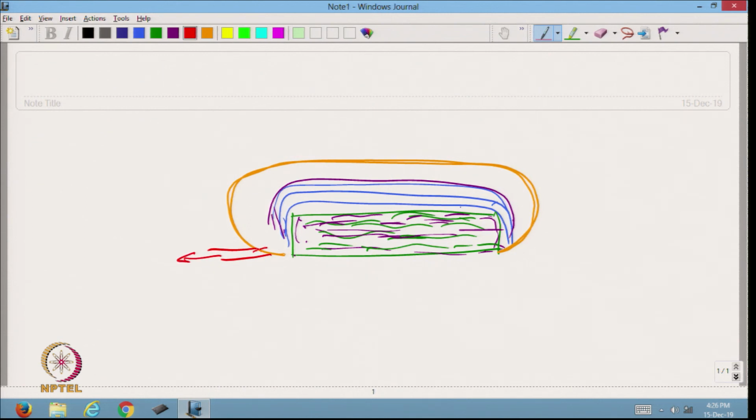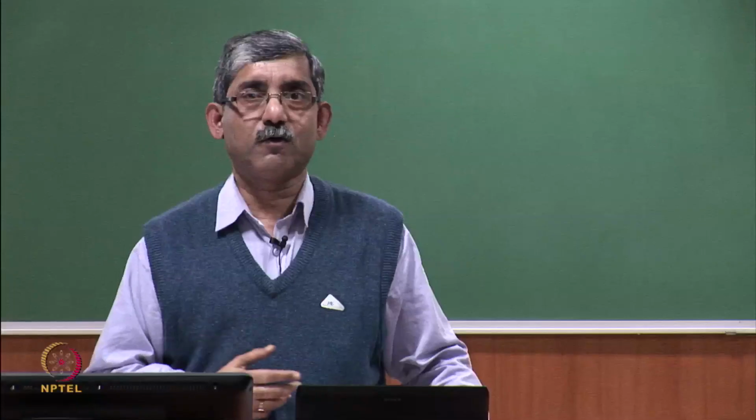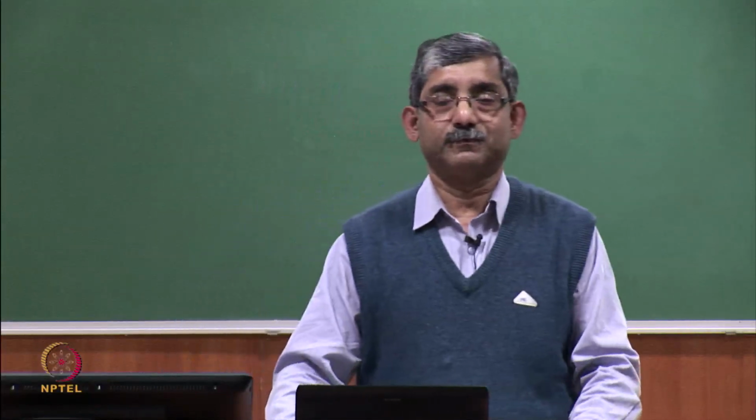So, as air is taken out, this will get compacted due to the atmospheric pressure, and the composite will get compressed, and finally, whatever voids are there, the air bubbles will come out and composite formation will complete.